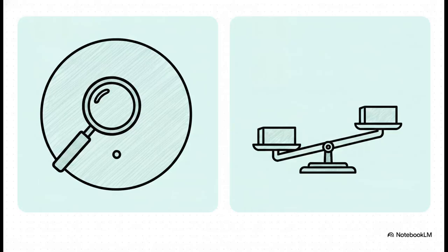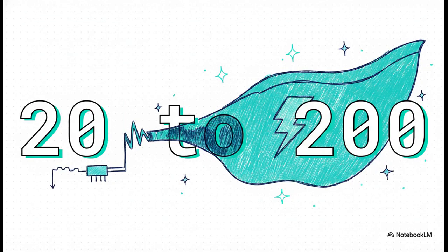This leads us right into two vital ratios we use to measure how a transistor behaves. First up is DC beta. This is the ratio of the DC collector current to the DC base current. Think of it as our current gain. On the flip side, we have DC alpha, which is the ratio of collector current to emitter current. Now, because that collector current is always slightly less than the emitter current, thanks to that tiny base current splitting off, alpha is literally always just a hair under 1, usually hovering around 0.95 to 0.99. But DC beta, that is where the real magic happens.